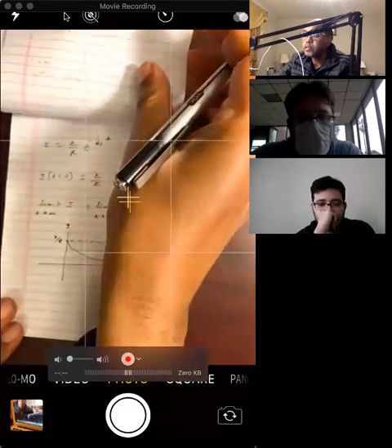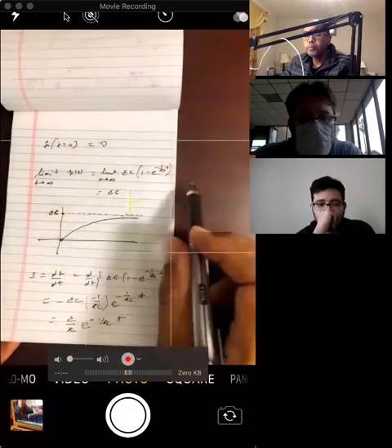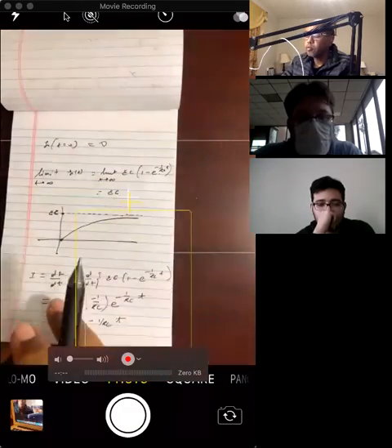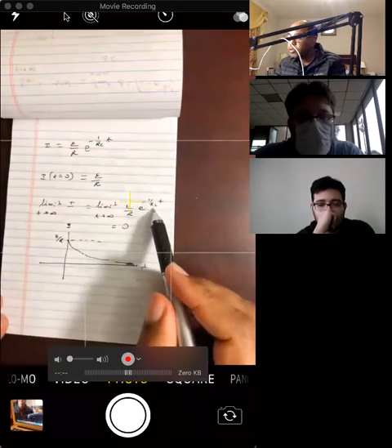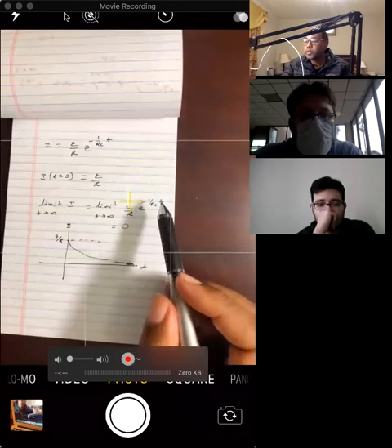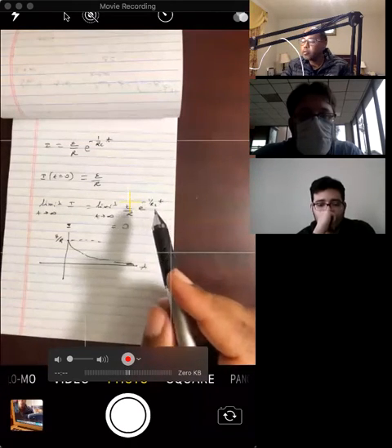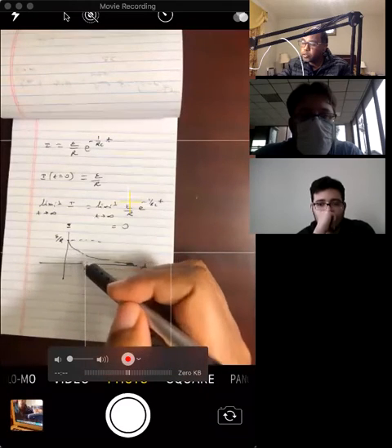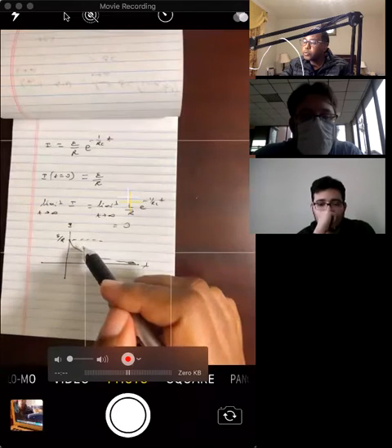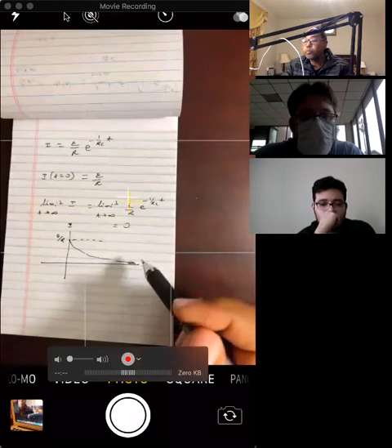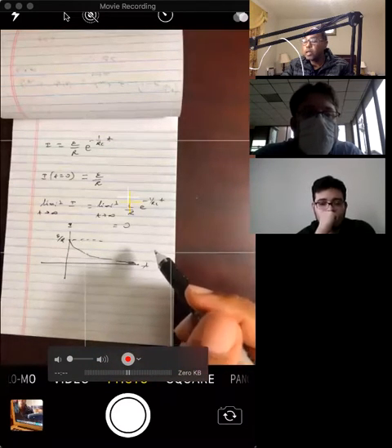So this is the graph of current versus time. Okay. So you see the charge builds up as time goes on, while the current starts at the maximum and then drops to 0. Now I want to tell you a little bit about this one. This factor over here, 1 over RC, controls how fast it's going to 0. If this is a very large number, it's going to drop to 0 very, very quickly. If this is a small number, it drops to 0 very slowly. So it's an important quantity. It's called a time constant.